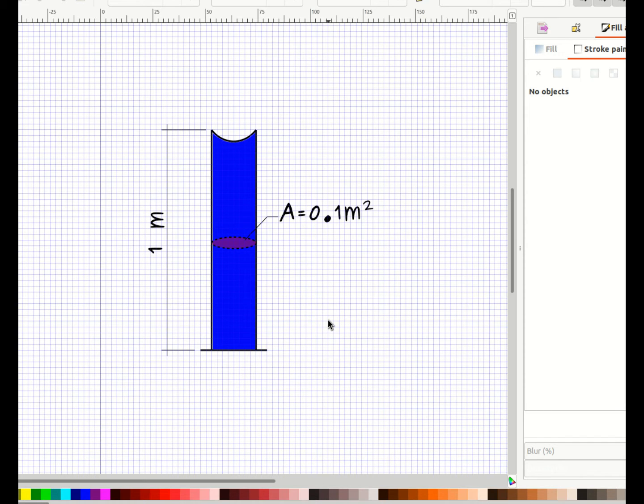The particle feature that I'm going to use basically assumes discrete particle settling. So the settling velocity is constant, and that's what we're going to provide. And I'm going to give, let's say, a 10 meters per day settling velocity.